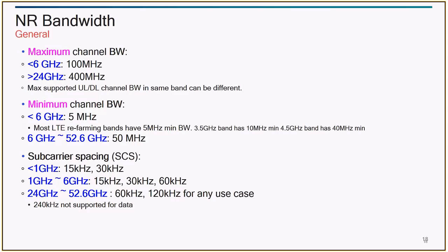At least when you deploy 5G, there has to be some benefit, right? So in terms of throughput, you would not see any throughput difference even, say, if you have a 5 downlink CA LTE mobile and an NR 100 megahertz. You would not see any throughput difference, probably just 1 or 2 Mbps sort of difference. The real kicker or sucker punch from 5G comes because it can aggregate bandwidths of as high as 400 megahertz.